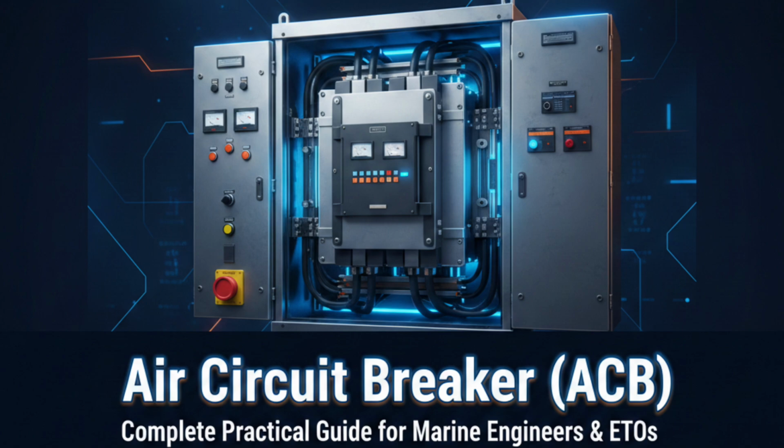In ships, ACBs are normally used as generator breaker, bus tie breaker, main incomer breaker, and emergency switchboard breaker. ACB is the guardian of the switchboard. If a short circuit or overload occurs, it reacts instantly and isolates the fault. Without ACB, a simple short circuit could damage generators, burn bus bars, or cause complete blackout.